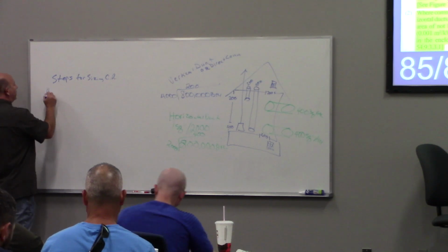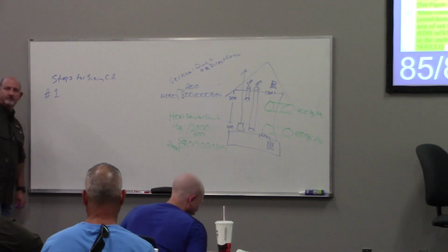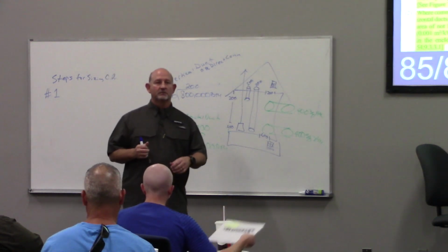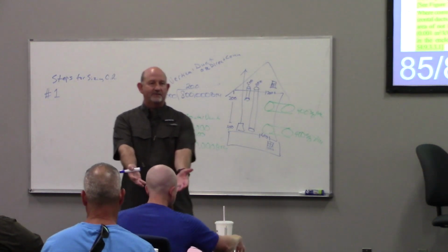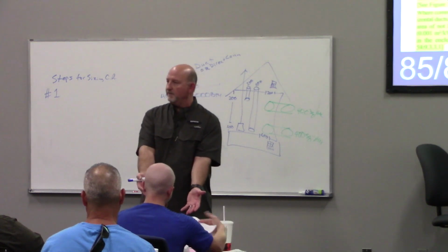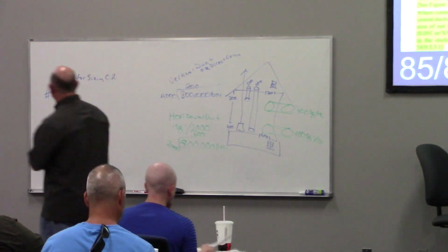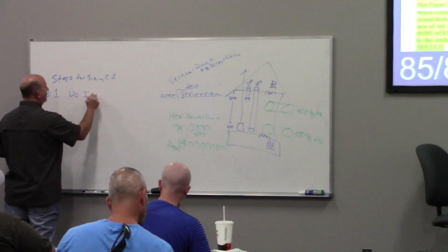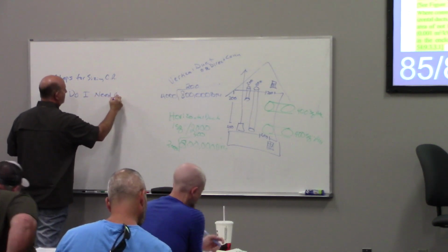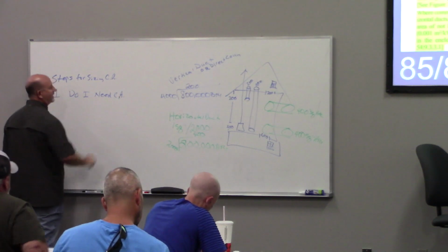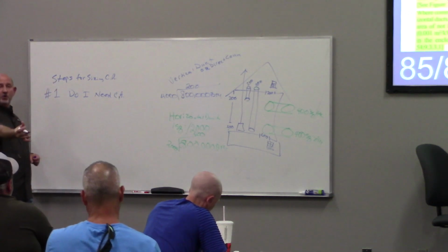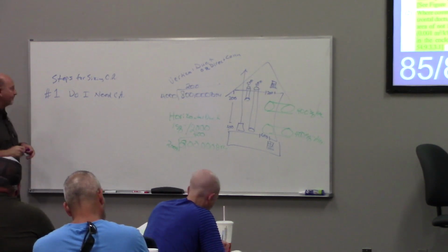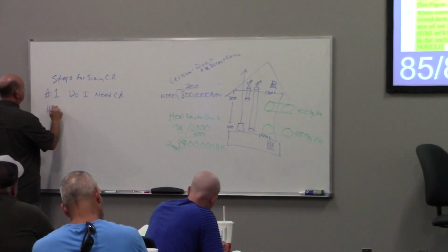By the way, what do you think step number 1 is? The very first thing to consider is, look at me, what if the room's big enough? I don't even need combustion air. Agreed? So step number 1, or question number 1 is, do I need combustion air? And again, don't abbreviate that, spell it out. So do you agree if my room is 50 cubic foot per 1,000, I don't need it? Agreed? Done.